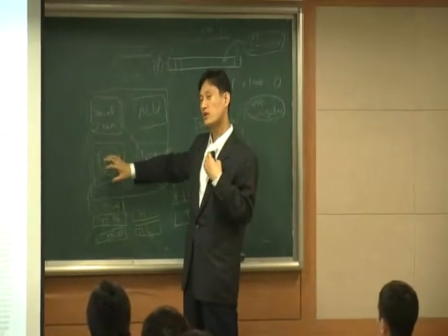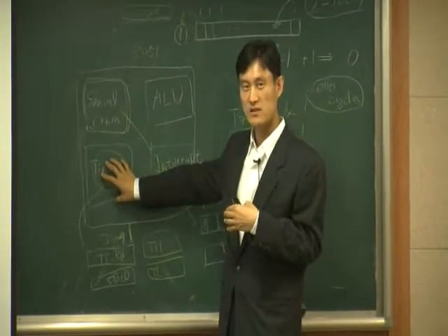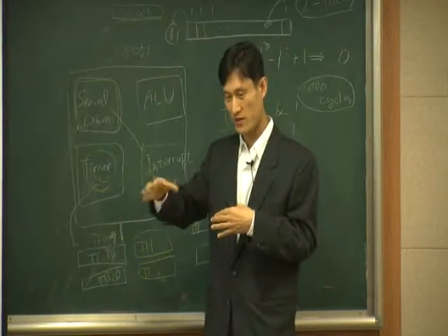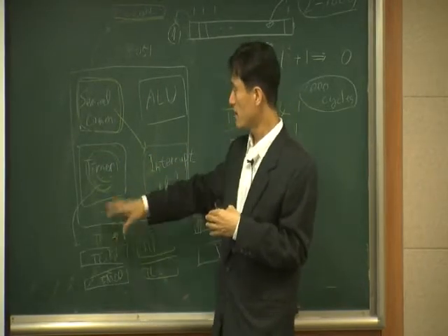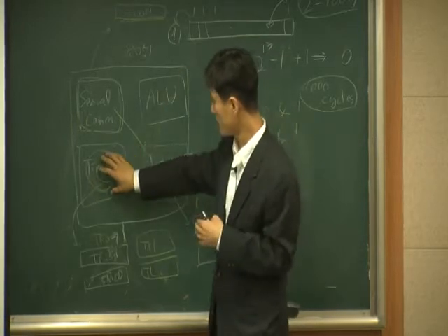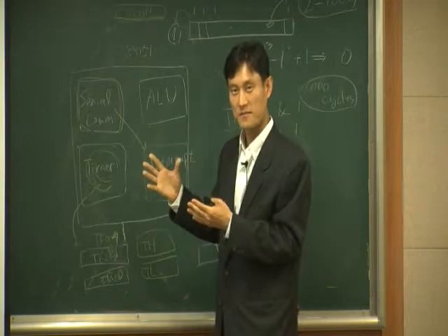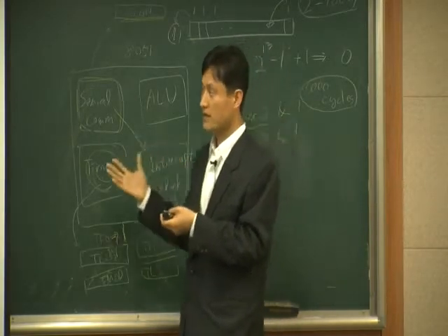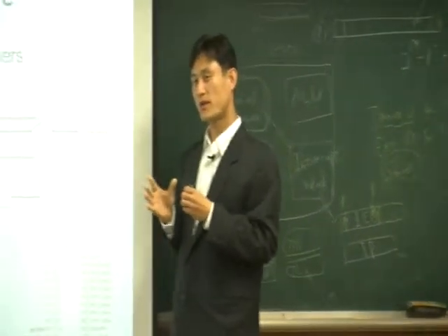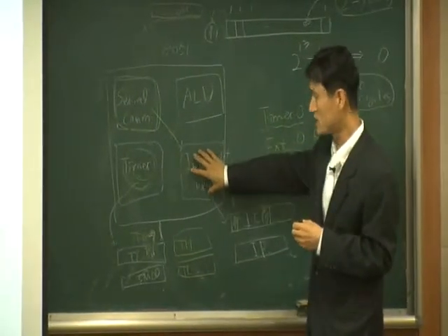Because what we want is to measure 1 millisecond. So you program it that way. And this hardware will run to measure 1 millisecond. And as soon as this overflow happens, the TF0 bit becomes 1. Same as before. But in this pure hardware technique, the difference is that now you program this block.